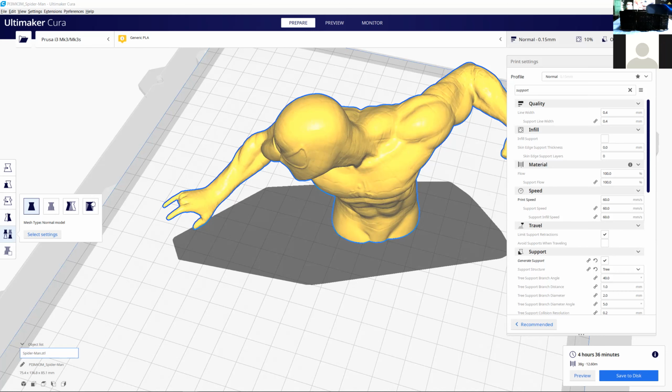usually a tool like this. You can slide underneath and keep prying at it till it pops off the bed, and then you're able to take it off. But usually the adhesion's really easy to tear apart. If I just pull, it'll come off. And this is with those zigzag supports down here. For something like that, I'd first see if I can just pull some of them off.